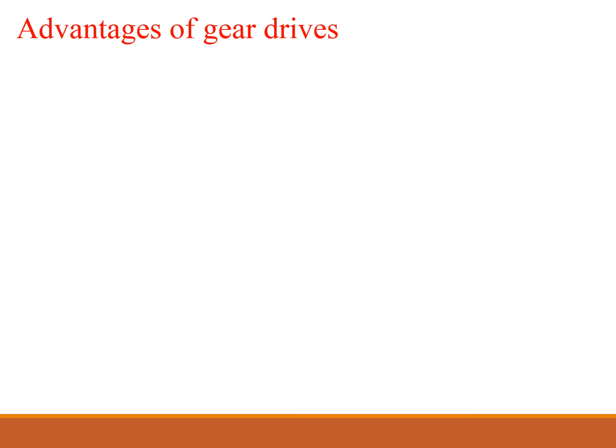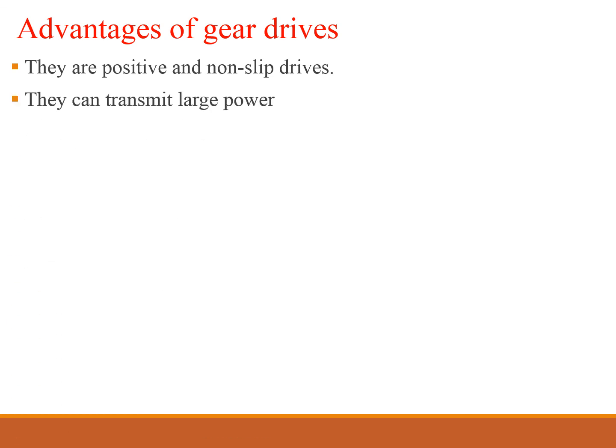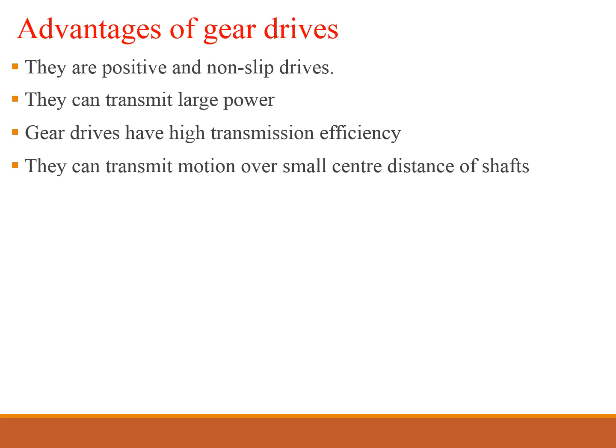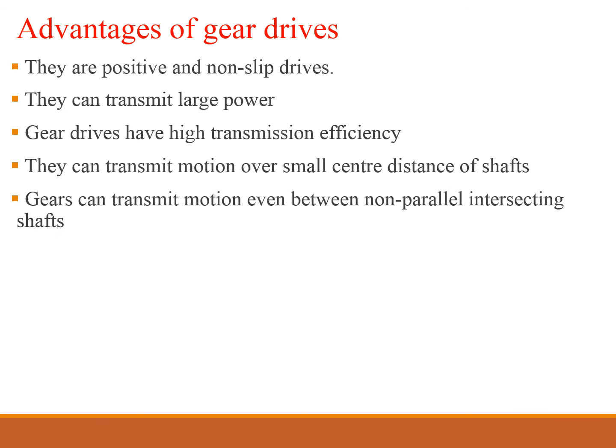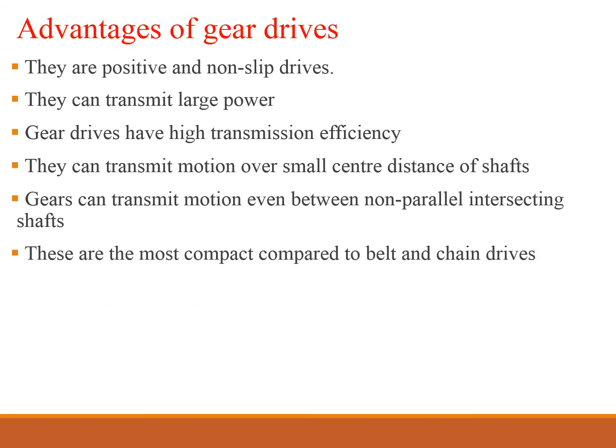Advantages of gear drive. They are a positive and non-slip drive. They can transmit large power. Gear drives have high transmission efficiency. They can transmit motion over a small center distance of shafts. Gears can transmit motion even between non-parallel intersecting shafts.